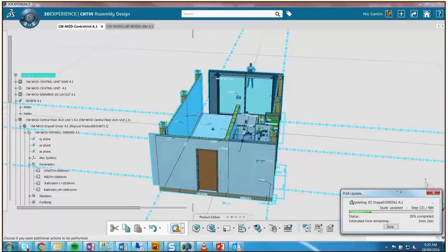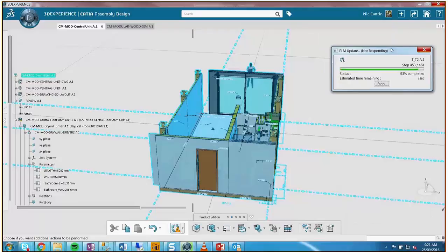So that returns a little red or green light, and it's not very useful in a single physical product like this. But if you were using a product template and knowledge pattern to instantiate a bunch of these different modules, based on just profile outputs, then you'd be able to instantiate all of them quickly and have a check to verify, based on your internal code compliance or quality assurance checks, that you're within certain design parameters.